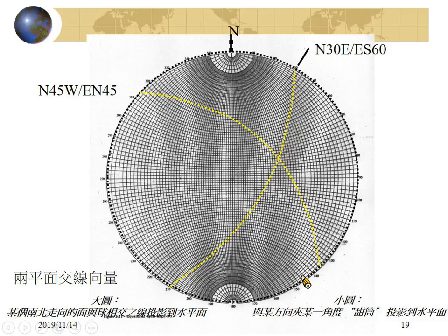Okay, so if you have two planes and the rock wedge falls, please tell me the vector of this wedge sliding down. The wedge will slide down along the intersection line, right? So please tell me the move direction of this block.